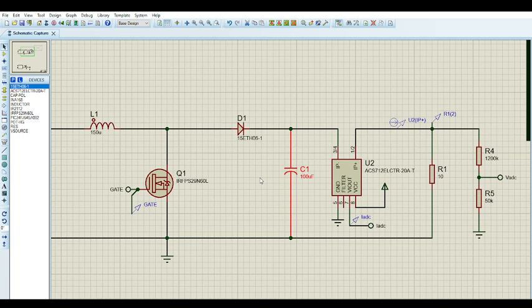That value you calculated is fine. Obviously, you have to go more than it to take into account parasitic resistance, and you have to parallel the capacitors to reduce the parasitic resistance of the capacitor, and you have to go 3 to 4 times higher, I guess, or sometimes 2 times is okay, but do not go so high, like to the thousands or the hundreds. Obviously in this case I have 100 microfarads, which is quite high. If you're gonna go crazy, don't go past 100 microfarads, because it will compromise your control. It will compromise it heavily.